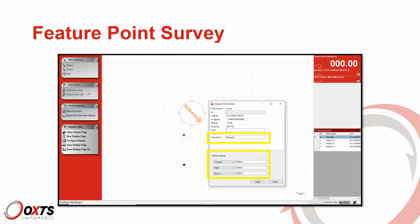It also gives you an option to offset the position. So if you've set up the survey trolley and you've pushed it as close as you can to the point which you want to survey, but there's some sort of barrier that's preventing you from getting any closer, you can just measure from the RT to the feature point and then introduce an offset this way, so that the position of that feature point is accurate.